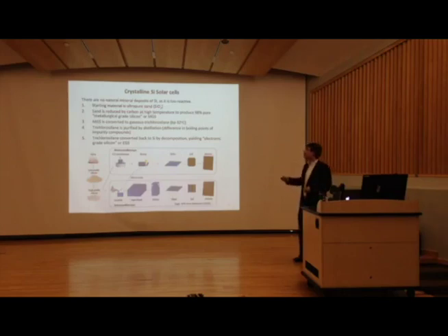So in this case, you want to use ultra-pure sand. Starting from that, you go through a high temperature reduction process to get 98% pure silicon. We call it metallurgical grade silicon, MGS. That's this one. And then you go through another purification process, the distillation process.